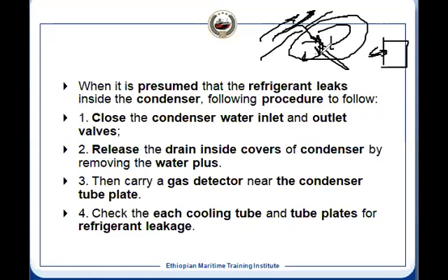But this sensor, we can put in this position. When the gas is leaking, the turbulence will be there, which means we can keep a certain distance. We don't have to keep it exactly on the surface of the piping, because it is coming out with high velocity. Though it is coming out, we cannot hear it, so this sensor will detect. We can keep it at a distance. The sound inside will stay inside and will not come out. It will not make any turbulence in the atmosphere, but it will detect the turbulence in the nearby atmosphere. So suppose there is another leakage, for example, it can detect that.